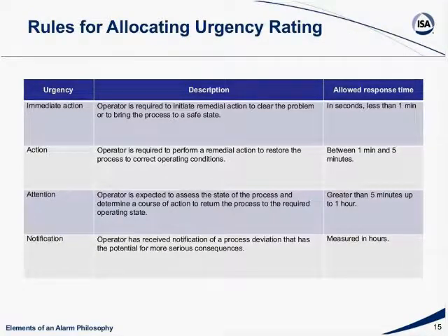So that establishes now the ranking for the severity of the consequences. Now we're going to talk about how you allocate an urgency rating to these things. Well, immediate operator action typically is measured in seconds, typically less than 1 minute. And this is something that operators are required to initiate a remedial action to clear the problem and bring it to a safe state. It has to be done immediately.